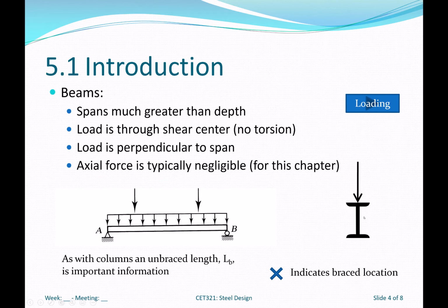So spans are much greater than depth. Again, span to depth ratio is about 12 to 24. And again, you want to make this depth in feet. All right, the depth is in feet.